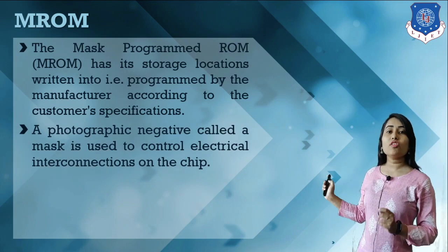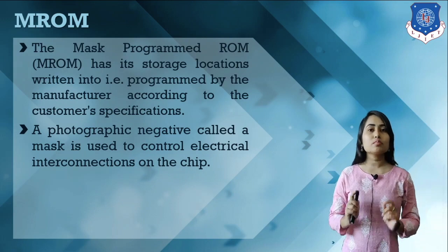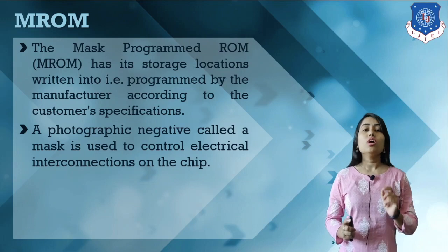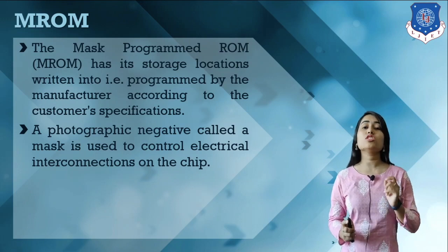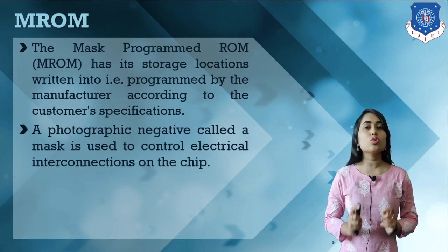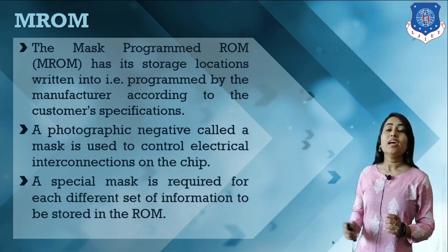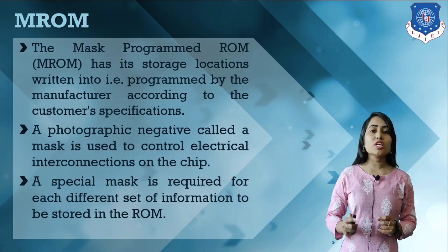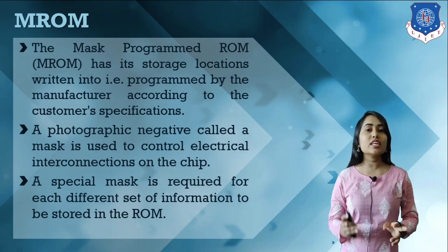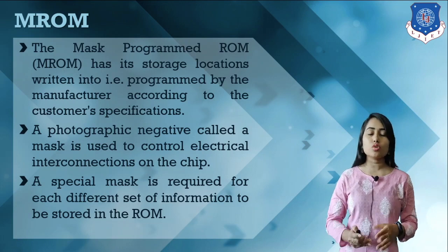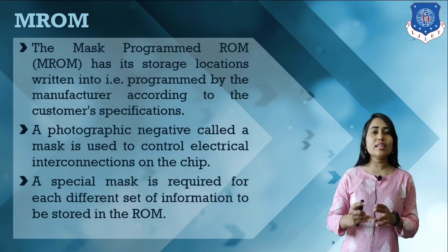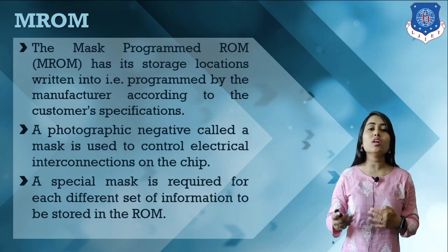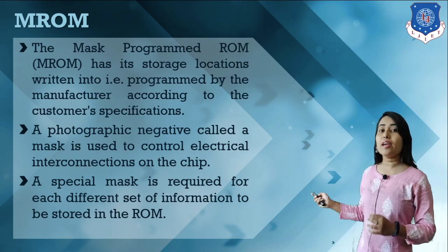Here a photographic negative, which is known as a mask, is used to store the information, and for each and every binary pattern or each and every bit, a special kind of mask is used to store the information. This mask basically stores our information at the manufacturing side according to customer specifications, and once the data